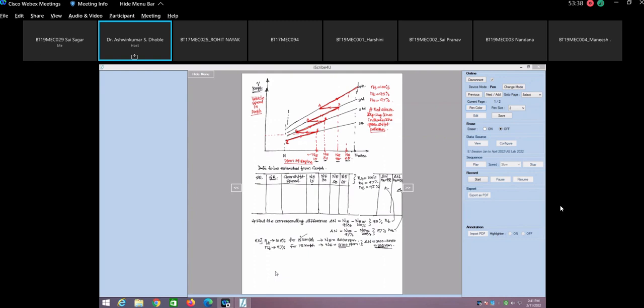Therefore people say that fuel efficiency also depends on the driving habit. Those who understand this correctly will not put the foot on the clutch pedal when driving on the highway. They will allow the clutch to be fully engaged. Whenever they want to control the speed, only then will they put the leg on the clutch pedal.